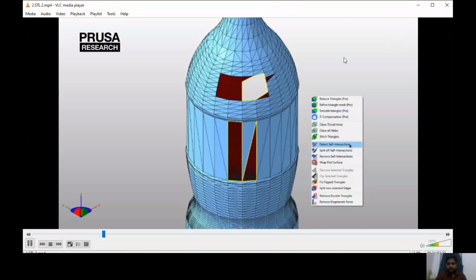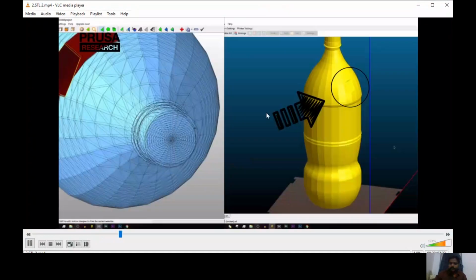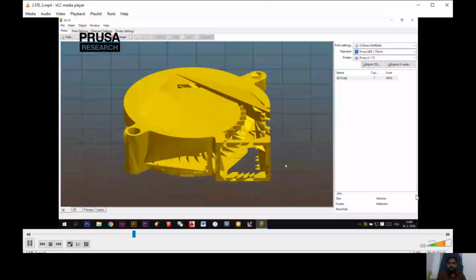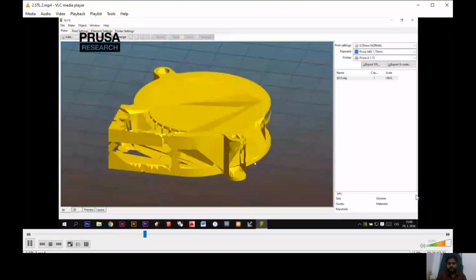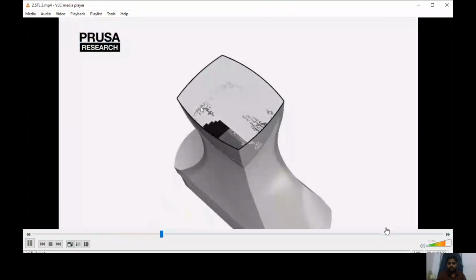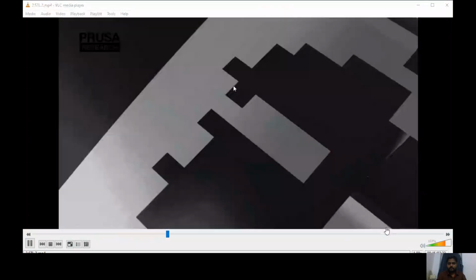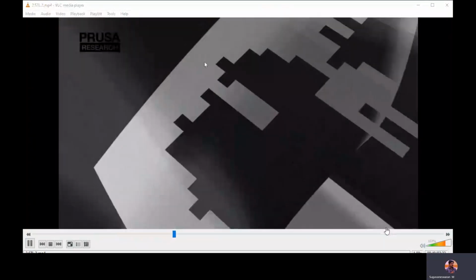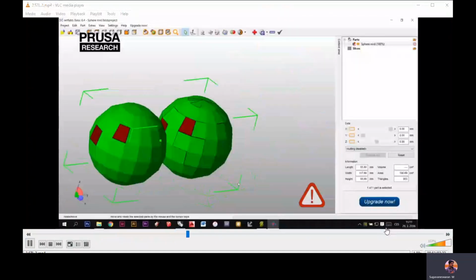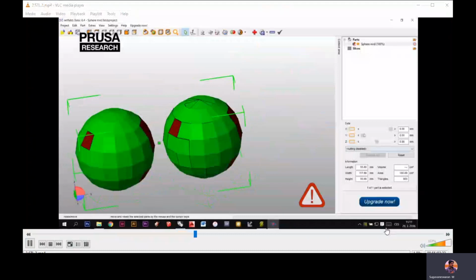A lot of modern slicers can partially fix some problems automatically, but if you do it by yourself, your model should be fixed when it is not solid. It means there are some missing triangles. A slicer can repair smaller issues, but you need to do it on your own if there are bigger errors. You can also find objects which were created from parts that were designed separately. Because of that, here you can find double faces. Models can also have triangles flipped inwards. The slicer therefore can't recognize the surface properly and will create a problematic G-code.